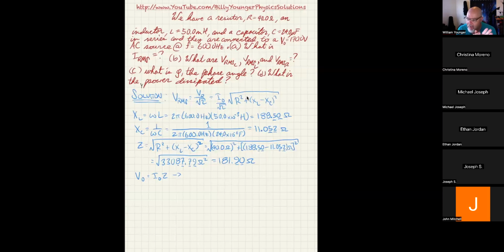That tendency is part of the reactance, but also part of the impedance. So the impedance is basically the equivalent resistance that takes into account not only resistance, but also the capacitive reactance and the inductive reactance.